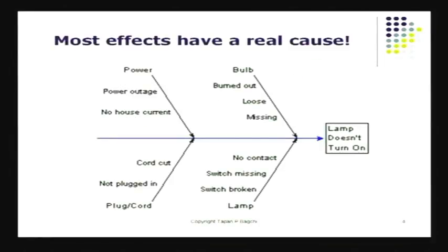The beginning, of course, is again this fishbone diagram, where I've got some speculation about how a particular process works, and I've listed out the factors here. And the output is on the right hand side, which is the effect of all of this. Now, if I have to study these different factors, I certainly need some special methodology. I cannot just do that the way ordinarily experiments are done. I cannot do that by manipulating one factor at a time. Just can't do that. I have to manipulate multiple factors together, because the real process has the involvement of all these different factors.